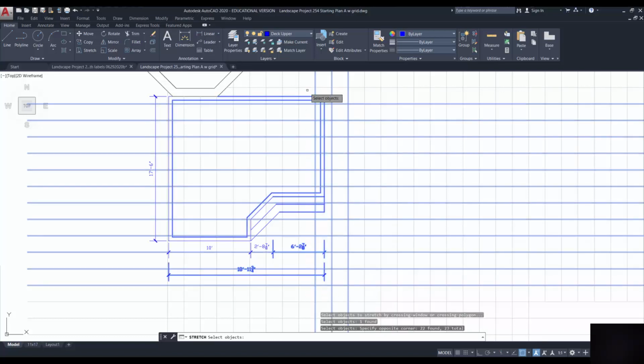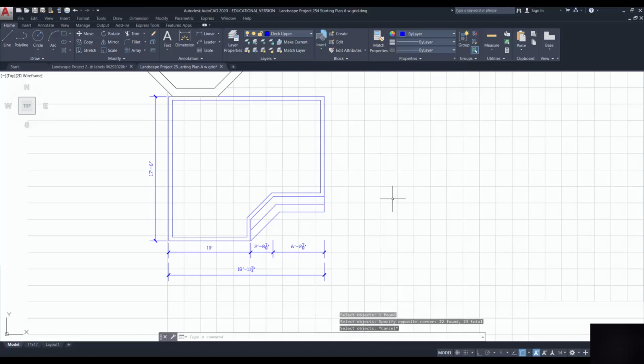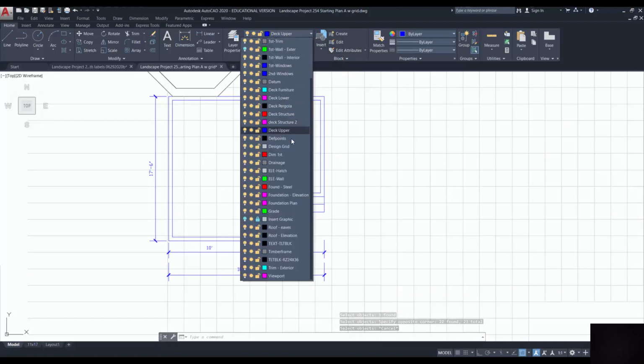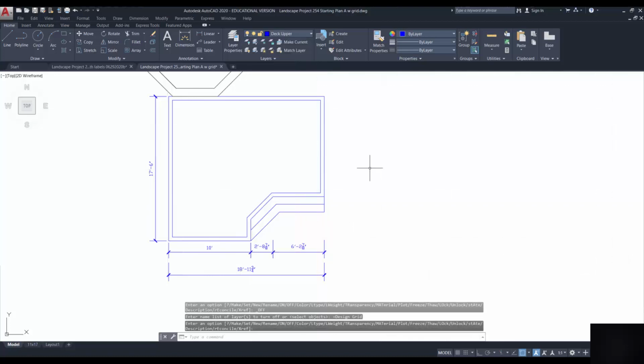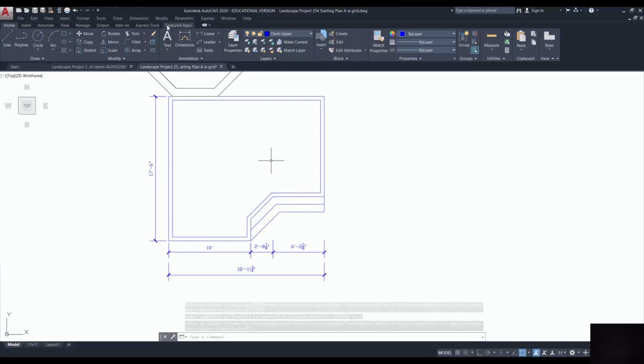Now, see how it's picking up the grid? Okay, I don't need that grid anymore. So why don't I do this? I'm going to go into that grid layer, design grid, turn it off. I needed it more for my sketch than I do for this. I can refer to the sketch design now. I don't need that grid.